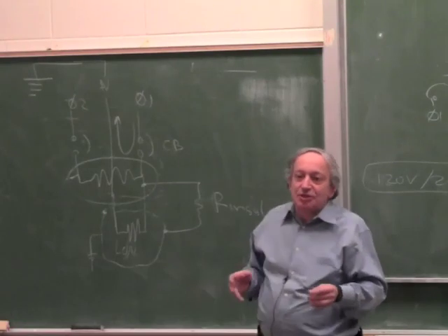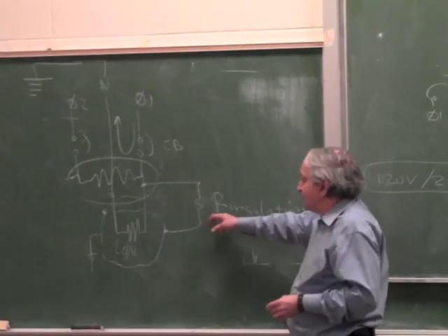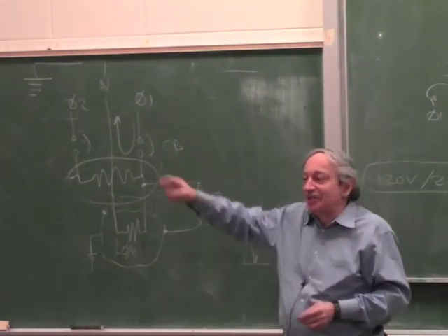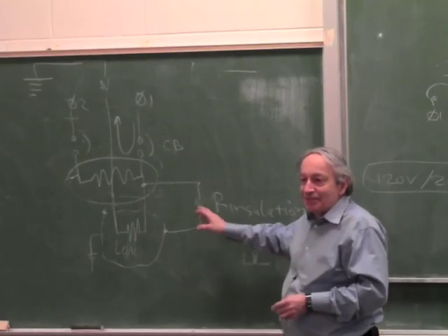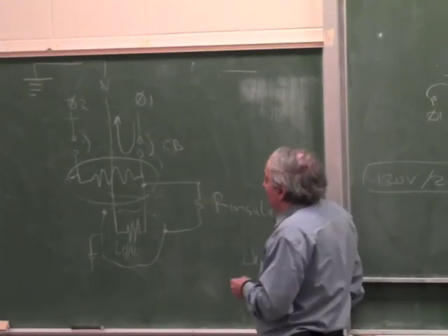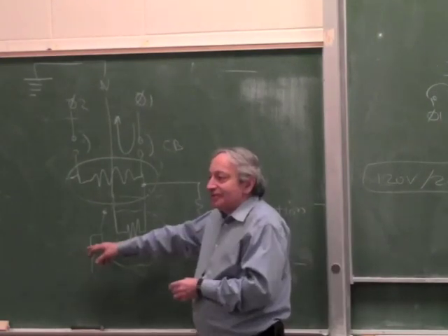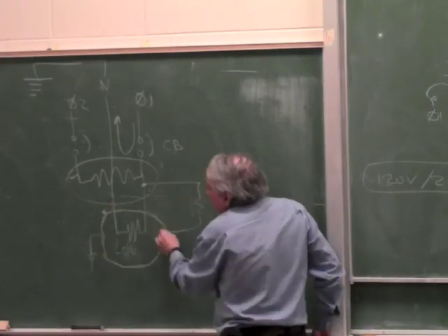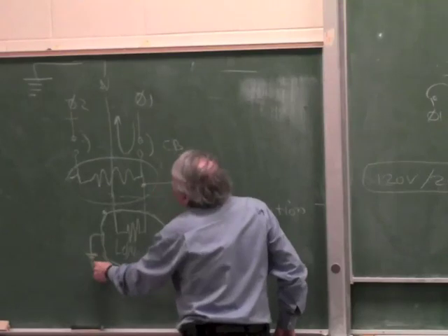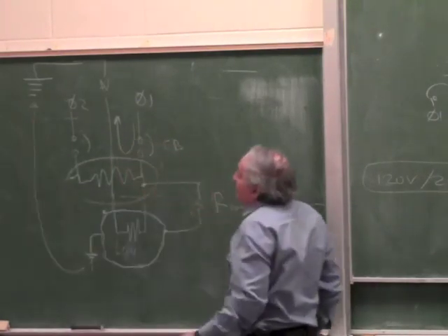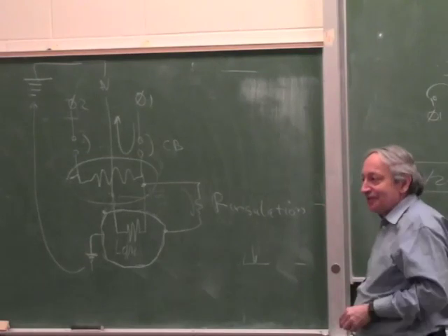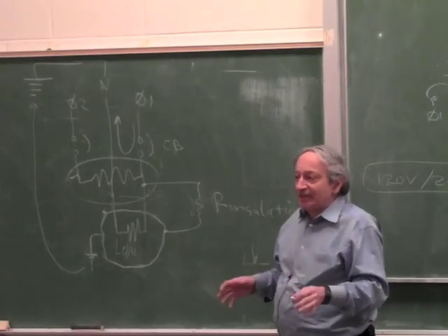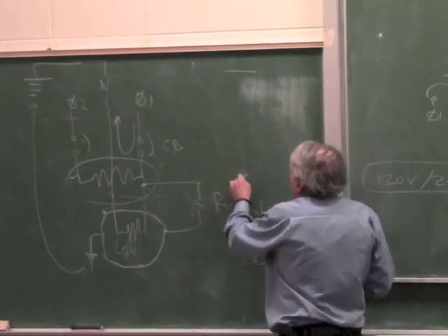And this happens because insulation is not perfect, and all the appliances in the house add up in parallel here. Right? Because the neutral and the phase go through the whole house, and each appliance has a bit of leakage. So it adds up to some current. So there is actually some return current through the ground because there is some leakage through the insulation. This leakage is connected to the ground, and this current flows all the way outside the house because it wants to return to the neutral. Okay, this current can be significant. Like the electrical code says that this has to be larger than 1 megohm.